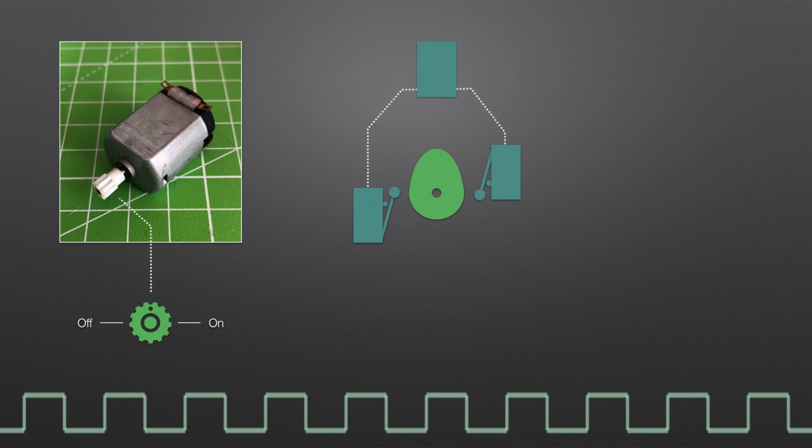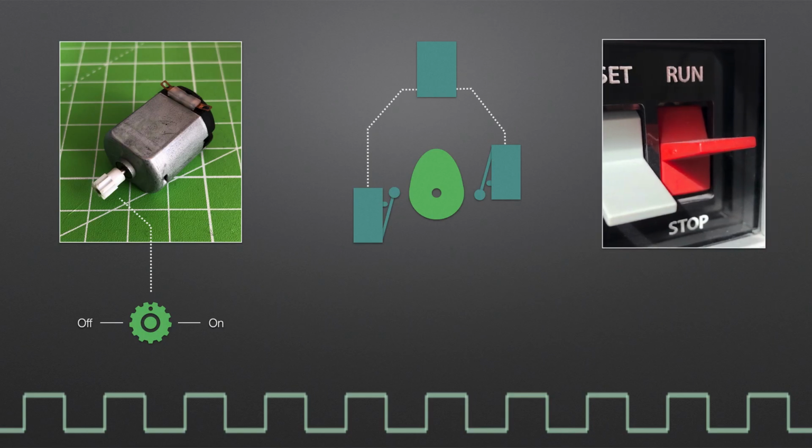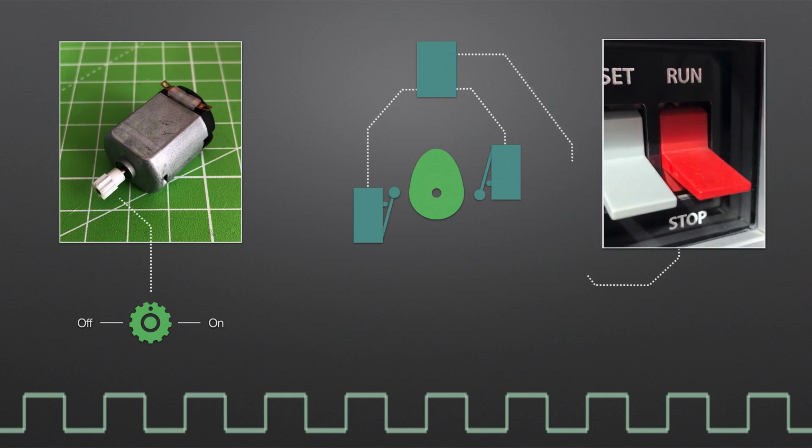That said though, when I stop the clock, I want it to pause in the off position, not in the on position, and this is so I can manually drive the clock via the front panel switches. I guess I could set it up so that when the motor power is switched off via the stop switch, some basic logic gates will keep the motor power going until it reaches the off position. Effectively, the logic will say if you're not powered by the switch, then take your power from the relay, which will ensure the cam stops shortly after the second microswitch.